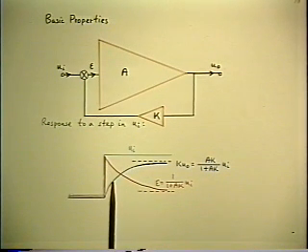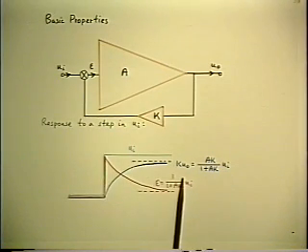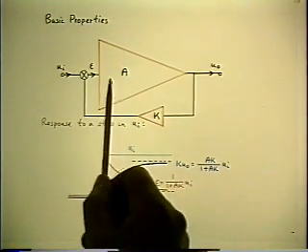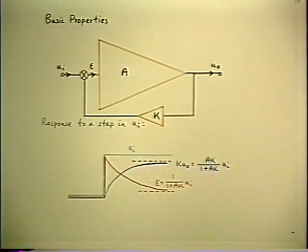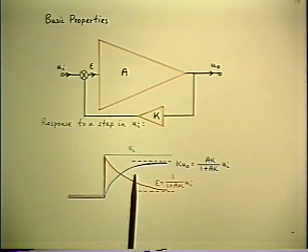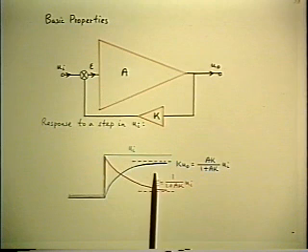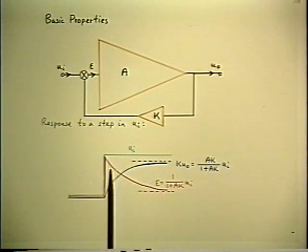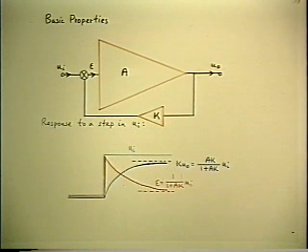What happens, of course, is the problem will divide down into a sequence of linear problems as one stage after another comes out of saturation or cutoff and recovers from the overload. The net result, of course, is the transient won't be a single exponential. It'll be a sequence of totally different solutions, probably mostly linear, because of current sources feeding into capacitors.